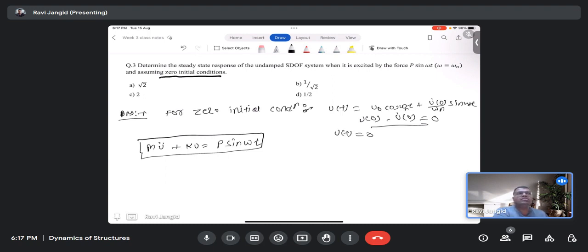If you are considering very high forcing frequencies, say for a high speed rail system, then if we ignore the transient response, the response will not be captured because the forcing frequency is higher. So in that case we need to consider the transient response as well, for that kind of system. Okay, sir. So in this we need to find out the response for the system.